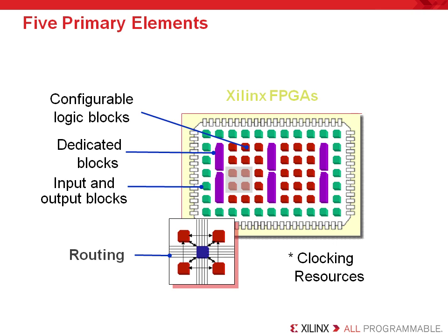Outside of the CLBs are large arrays of routing resources. The routing is connected together with switch matrices. The switch matrix allows many different lengths of interconnect to connect a signal from any source in the FPGA to any destination. This structure is designed to assure routing flexibility so that all designs can route to completion.